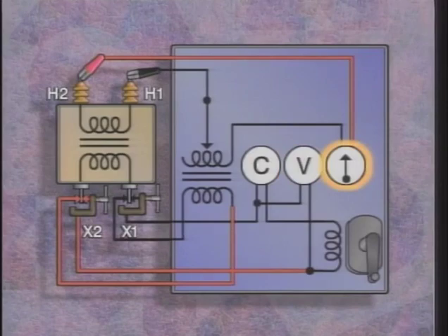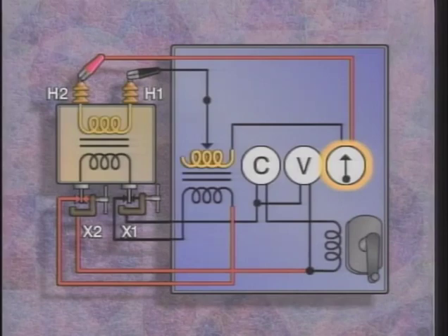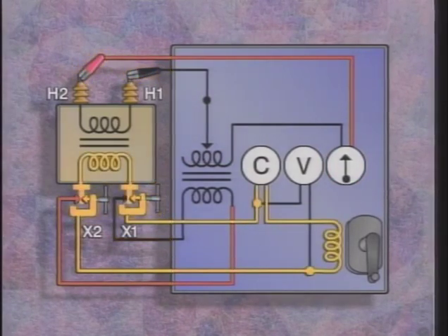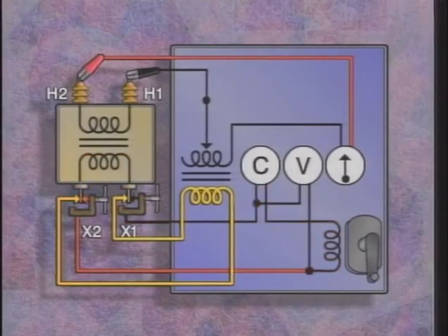It indicates the magnitude and direction of current that results from voltage that's induced in the high voltage windings of both transformers. Also included in this illustration are test leads. One pair of the test leads, called the exciting leads, contains 2 conductors that are used to apply voltage from the generator across the low voltage winding of the power transformer. These same test leads contain another 2 conductors that are used to apply the generated voltage across the low voltage winding of the reference transformer.